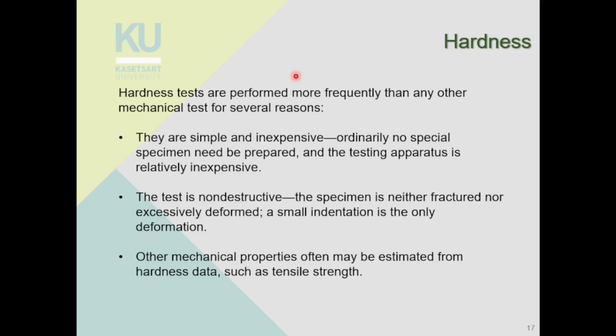And hardness testing is non-destructive. Non-destructive means you don't destroy the specimen. You can use that specimen again. The specimen is neither fractured nor excessively deformed. You only have a small indentation as the deformation, so you can reuse that specimen.